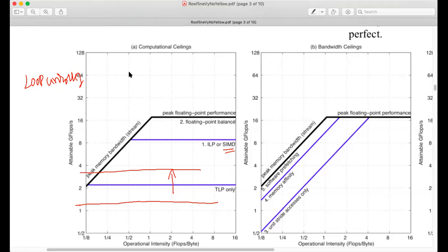Then after increasing the memory, there are 2 possibilities. It may give us more scope for more unrolling, or maybe no, we already did a lot of unrolling, and in spite of having got everything possible from the memory, that's the best we could do. At which point you may even consider decreasing the loop unroll factor and thereby save resources on your FPGA.